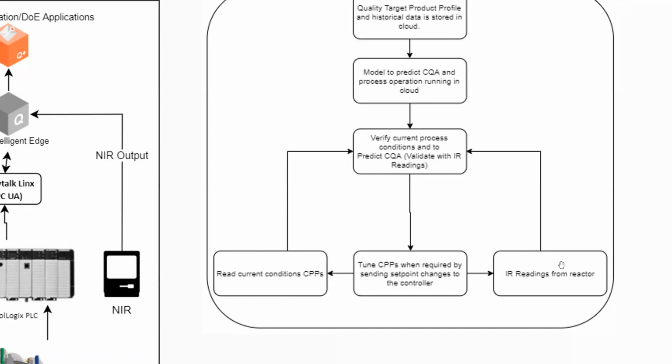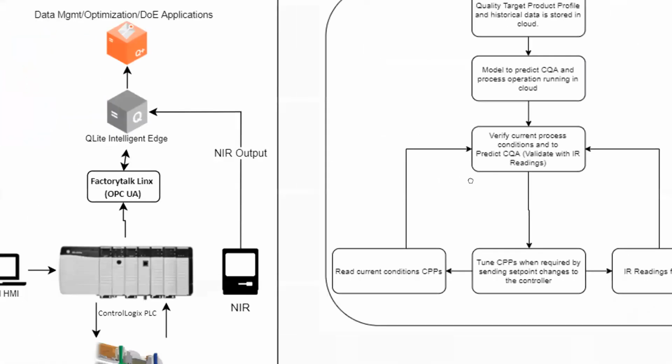Similarly, the IR readings from the reactor are also collected, sent up to the system, and used to predict a CQA, in this case, the concentration of the product, or at least verify that there are no impurities in the product, instead of taking an offline lab sample. All of this is seamlessly done with one edge device located